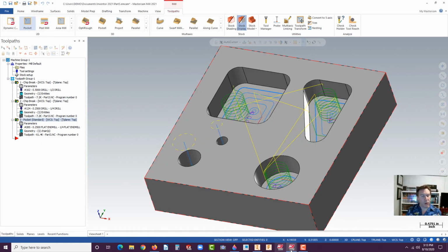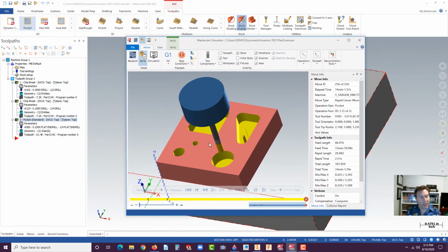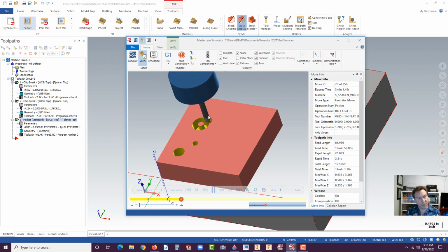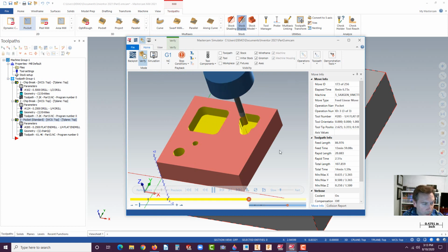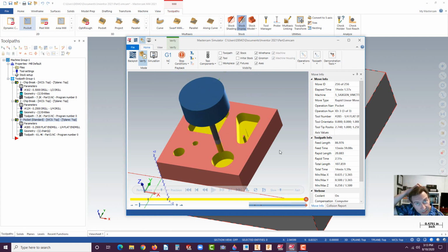Now, just to show you, our goal with Mastercam is this ultimately, where we could see the process. And this is a simulation. Let's go all the way back and hit play. And you can see it's showing, there's the actual tool. Right there, it's an end mill. It's a 1/4 inch end mill, and it's milling out those pockets. And it's finishing it. And then there were the 2 drill processes, which we set it to peck for chip break, so it would actually break the chip off so we could go with very high speed.